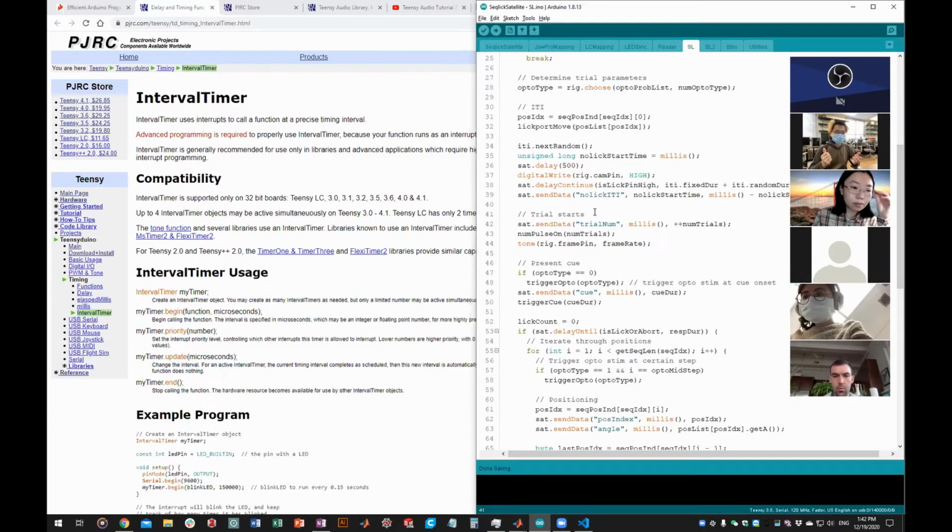Furthermore, we want to do something more. We want that pulse to represent some information about the trial number, like which trial we are in right now. The way I represent the number is by how wide the square pulse, or TTL, is. If it's 1 millisecond wide, that means it's trial 1. If it's 10 milliseconds wide, it's trial 10. But what if we have reached 1,000 trials? Then we will have a 1 second long pulse.